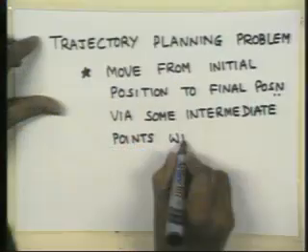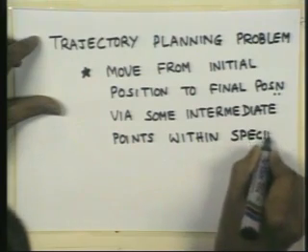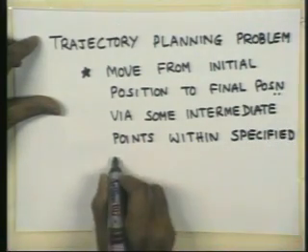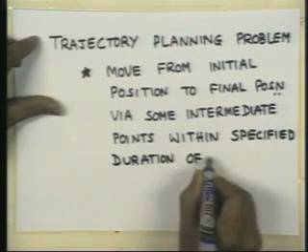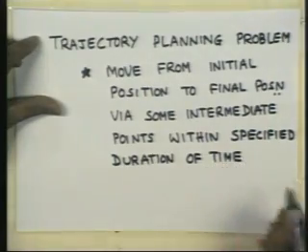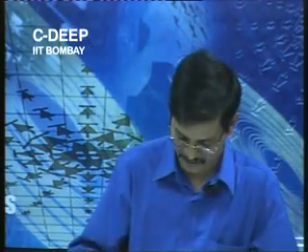So, in 3D space, you could ask this end effector also to move from initial position to a final position via some intermediate points within a specified duration of time, where you want to control the speed and the accelerations that are achieved. Subject to some constraints like we just now discussed.